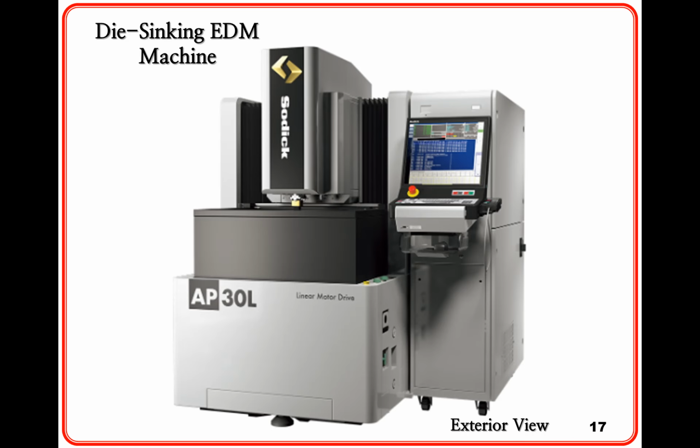In electrical discharge machining, the workpiece and an electrode made of an electrically conductive and relatively easy to machine material, such as copper, brass, or graphite, are placed in a dielectric fluid.